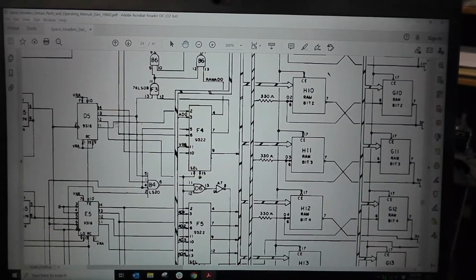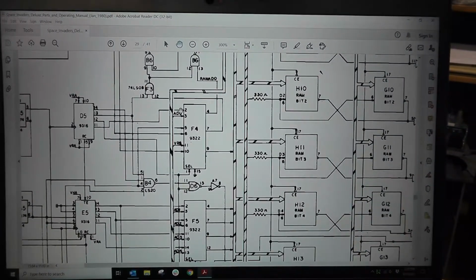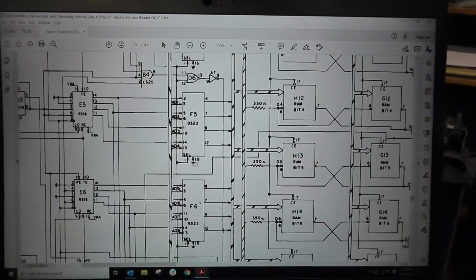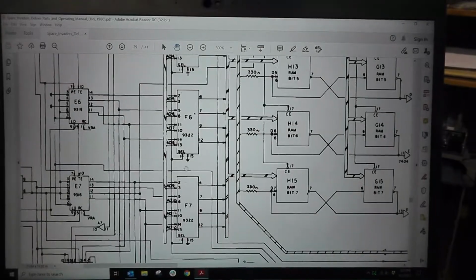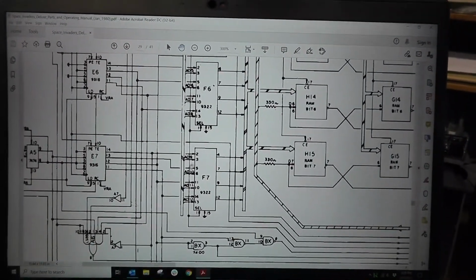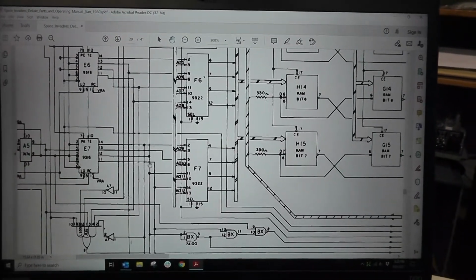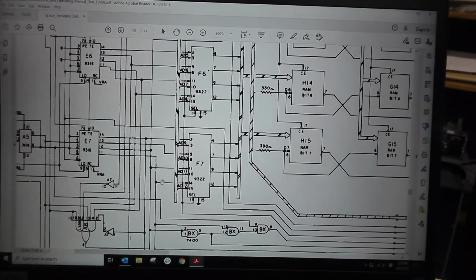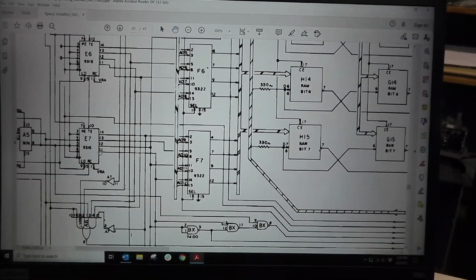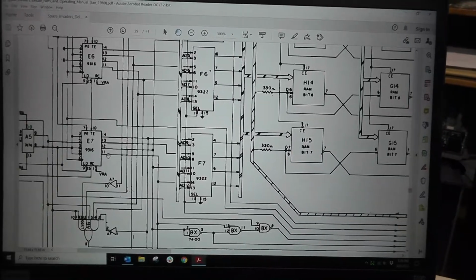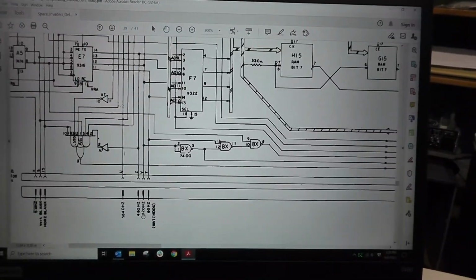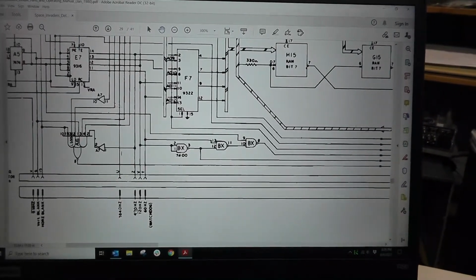Anyway, you can see here that you have these 9322s, these multiplexers, which are the same as 74157s, and you can see that some of the addressing comes from, like right here, this 9316, which is basically just the counter, which is also like 120 hertz or 480 hertz.